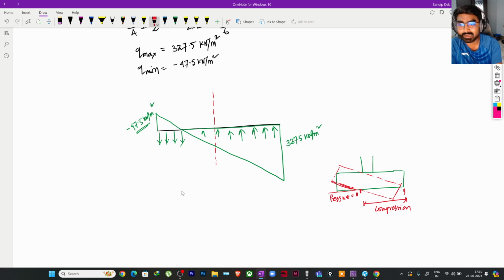So what we are getting from the linear analysis, this negative value, in the real scenario, there will be no negative pressure in the foundation, correct? So generally in the linear analysis, if I talk about the software analysis, we assume the soil as springs, right? And here my foundation is connected. So if the compression load is coming, it will provide resistance to compression, PR. And if there is any tension, it will provide tension resistance, I would say TR. Right, it is a linear spring.